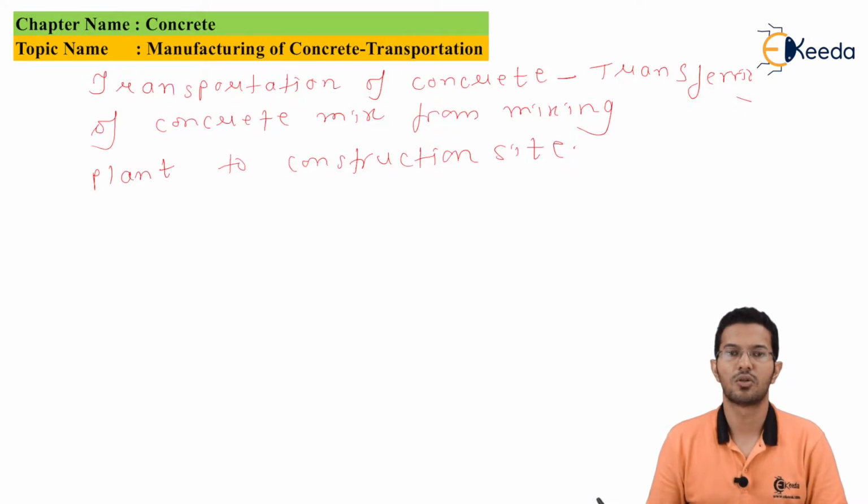At a central or portable ready-mix plant, concrete should be discharged from a truck mixer or agitator truck within 2 hours. If non-agitating transporting equipment is used, this time is reduced to 1 hour. All delays must be avoided in order to prevent honeycombing or cold joints.